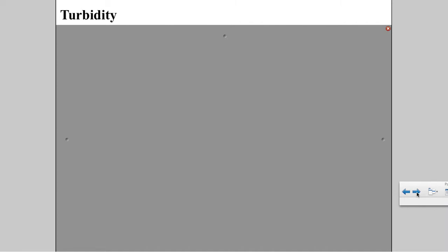Let me see, what's the temperature? What's the pH? Then the DO, the dissolved oxygen. What's the oxygen levels? Then the nitrate levels. What's the level of nitrates that's in the water? If it's too much, not good. If it's too less, not good. Has to be just right.